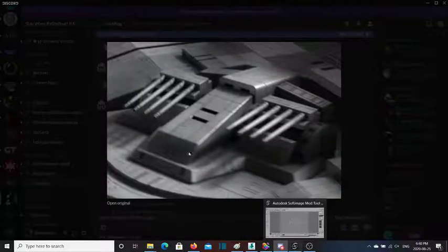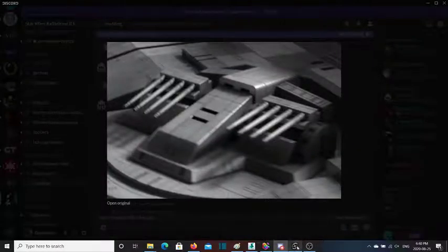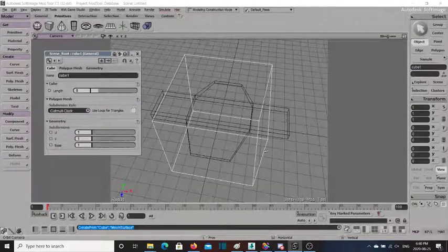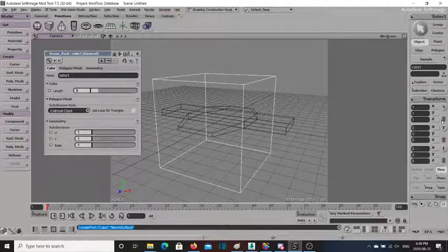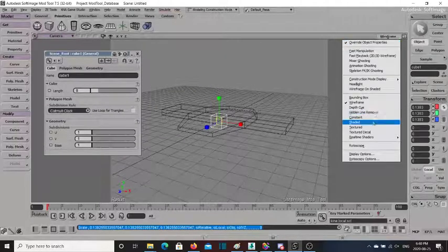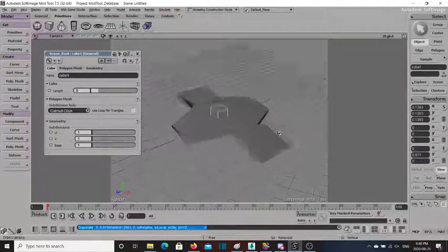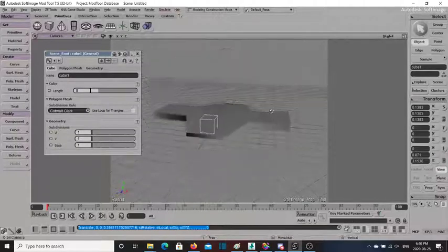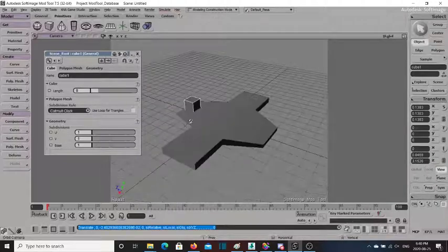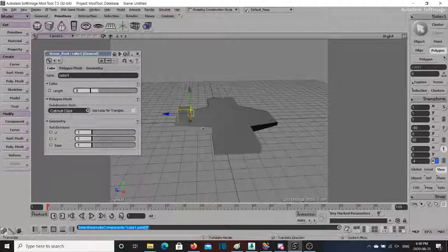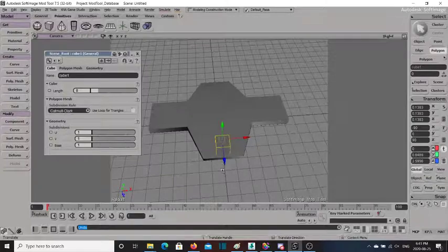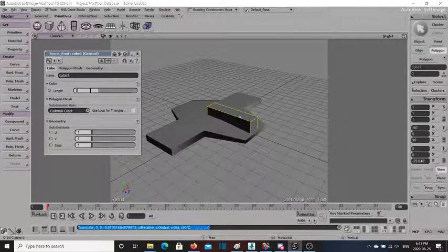Now, from here, I'm going to create this cube here. This is going to be mostly one cube. So I'm going to start with a primitive cube. I'm going to scale it to be about appropriate to what I want. I'm going to enter shaded mode so that I can see more clearly what I'm doing. I'm going to move forward along the Z-axis, look approximately where I want it, which is at the front of here. Move this downwards so that it's merging into the mesh. Move it backwards along the Z-axis. Sorry, it should be moved backwards along the global Z-axis. Excellent.